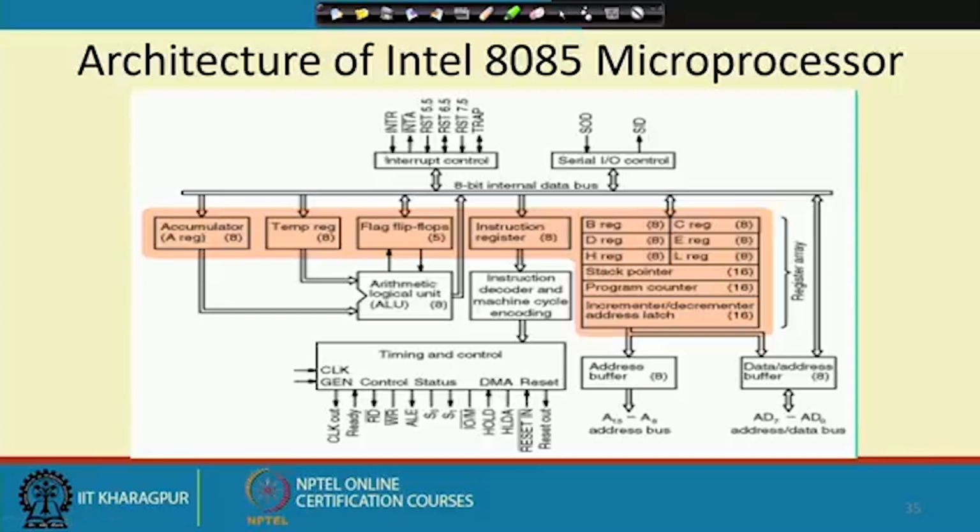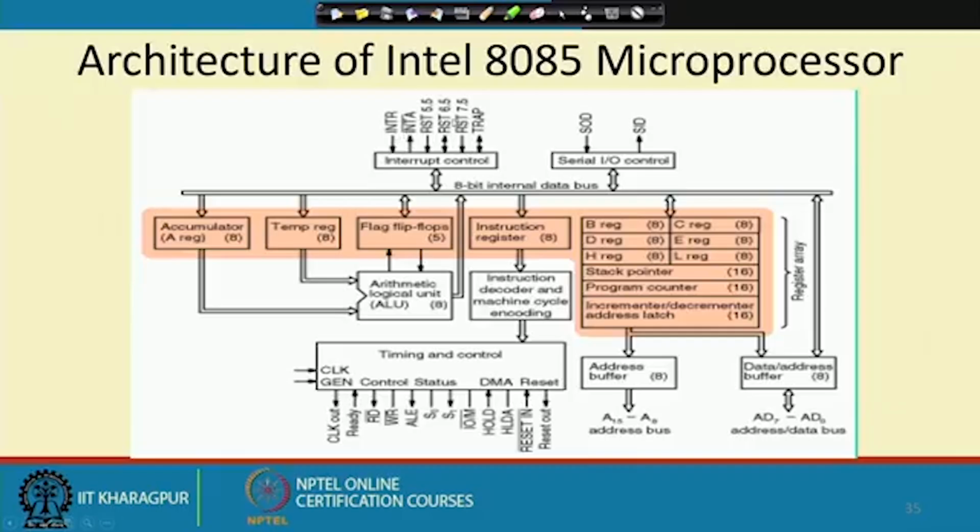If you want to tell the processor from the outside that something extra or something special has happened, and that has to be taken care of. For example, if this 8085 microprocessor is used for controlling the operation of a plant, and a smoke detector detects some smoke, then it can send an interrupt to the processor telling that some abnormal situation has been detected.